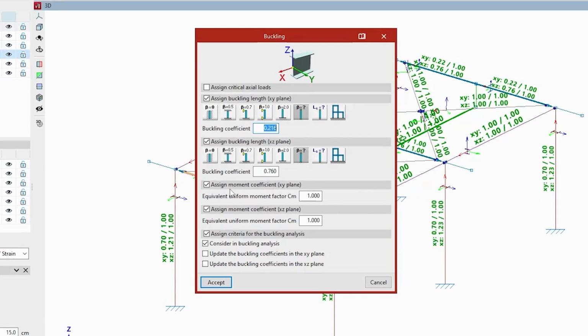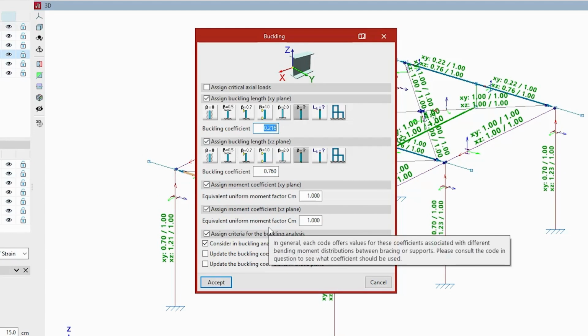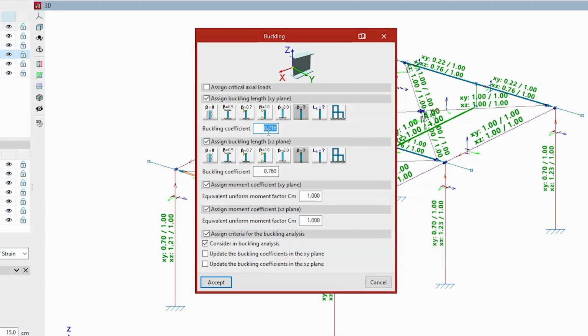As you can see, we haven't done any work on the buckling factors so far, and yet we have some buckling coefficients that differ from 1. That is because when we were exporting from Portal Frame Generator, remember that we selected that we want them to be in buckling in sway frames. So it has helped with the bars that came from Portal Frame Generator.